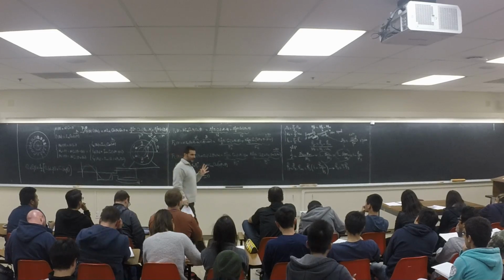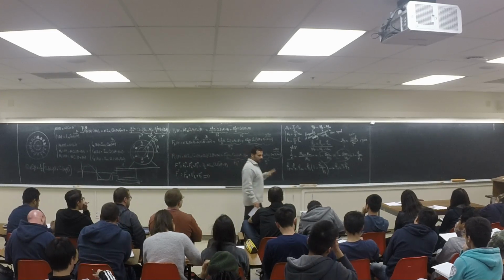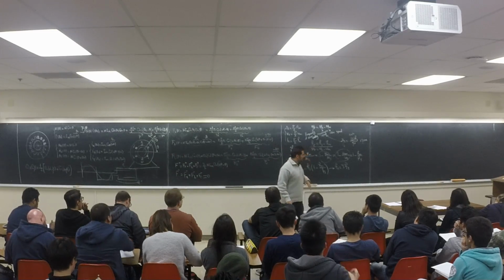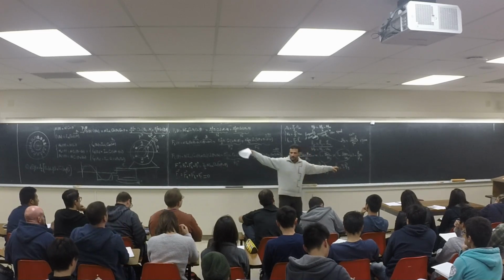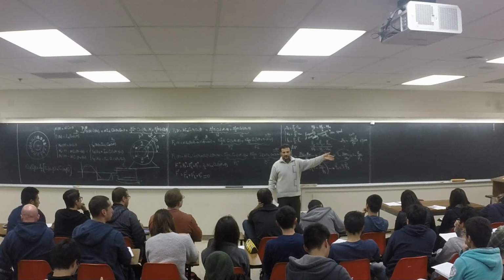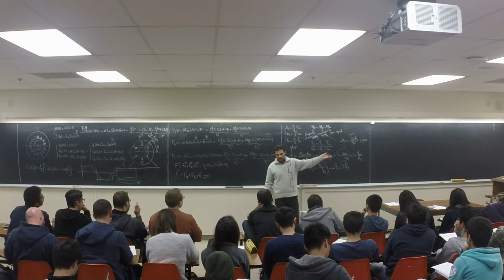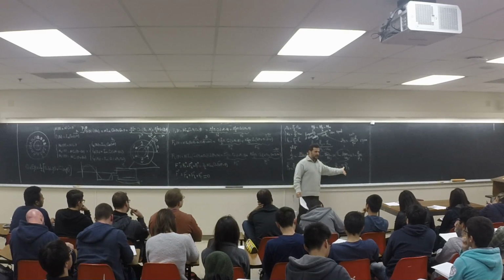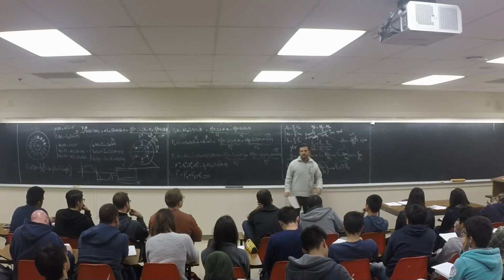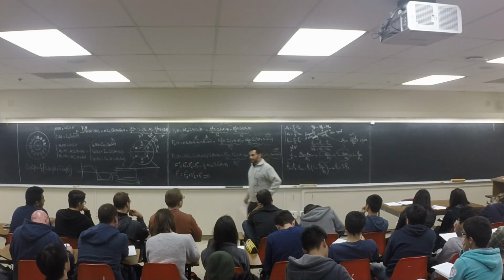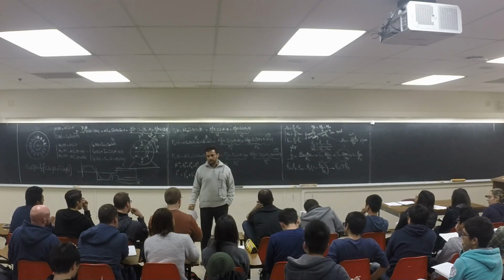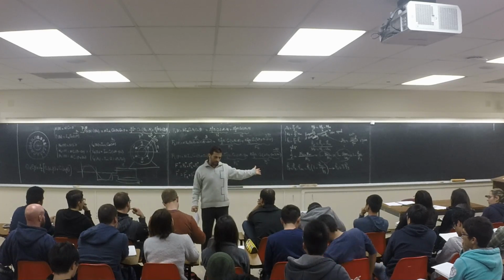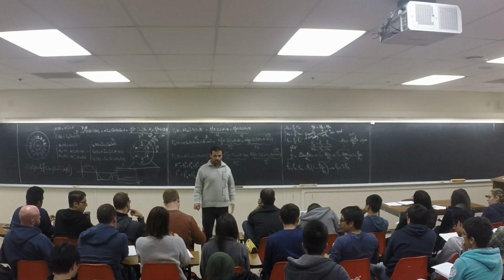We're going to get there, but 1%, worst case 5%. Let's say this is 60 hertz. Let's say the stator winding, we plugged it into the three-phase system here. How much is it? 60 hertz, right? And if the machine has 1% slip, how much is the frequency of the rotor? Almost 0.6 hertz, right? 60 times 0.01 is going to be 0.6 hertz.